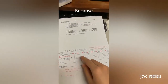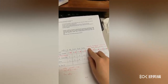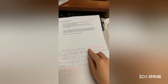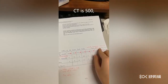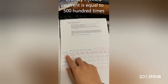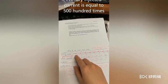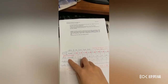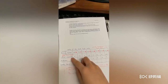Because the turns ratio of the CT is 500, the primary injected current is 500 times the actual injected current.